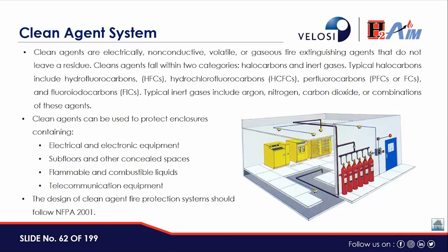Typical halocarbons include hydrofluorocarbons, HFCs, hydrochlorofluorocarbons, HCFCs, perfluorocarbons, and fluoroiodocarbons as well, FICs. Typical inert gases include argon, nitrogen, carbon dioxide, or combinations of these agents.